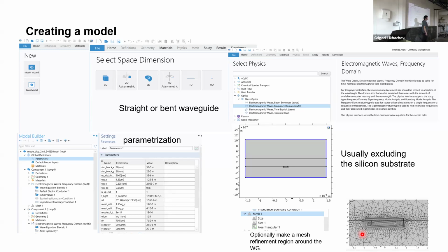Of course, COMSOL, like almost other PDE solving software in computers, needs a discretization of the space. You are creating a mesh, and just to point out a triviality here, only the inner box is for the actual dielectric silicon nitride waveguide. The outer box just defines a region to make the mesh finer within the box, so that you have a more accurate description of the fields closer to where the field should exist.